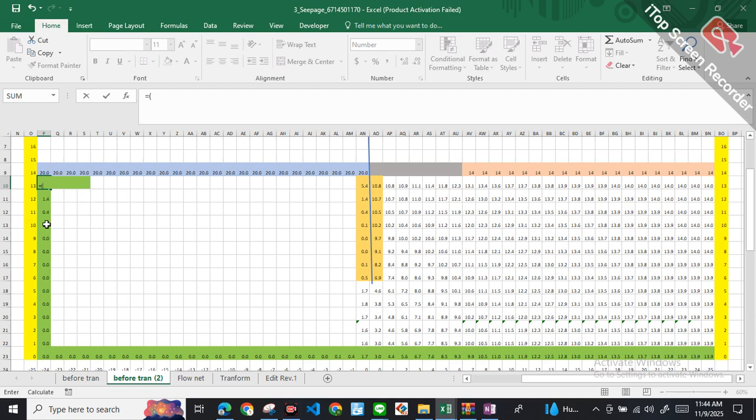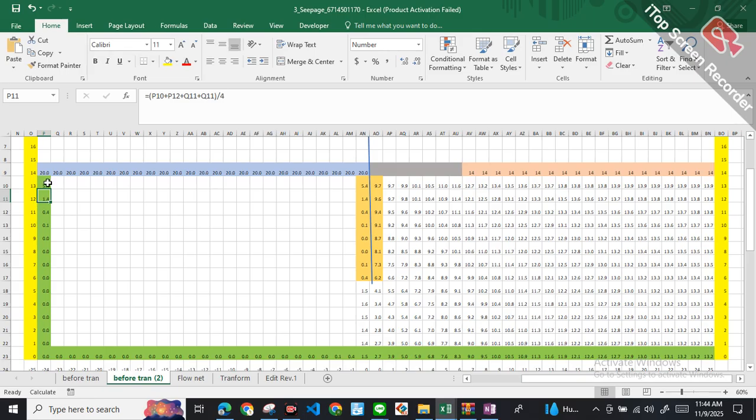So I'm just going to use my keyboard. Just press the up button of your keyboard, 20 plus, just move down plus, then go to the right cell plus. Now I technically need to go to the left, but since there is no boundary on the left, I go back to the right. Close your bracket, divided by 4, done. So this is how it happens.